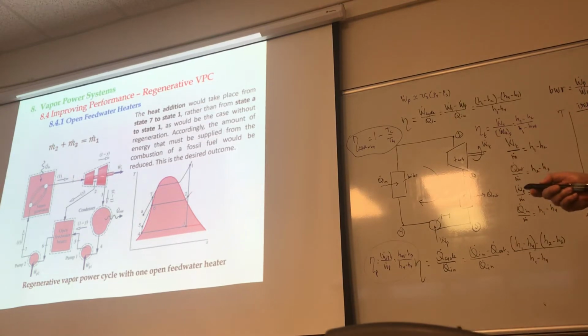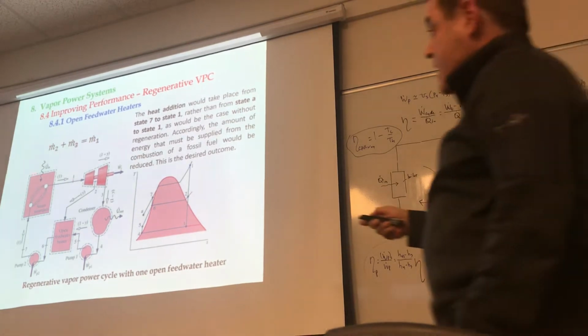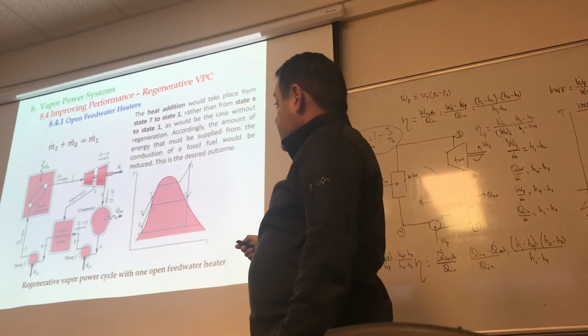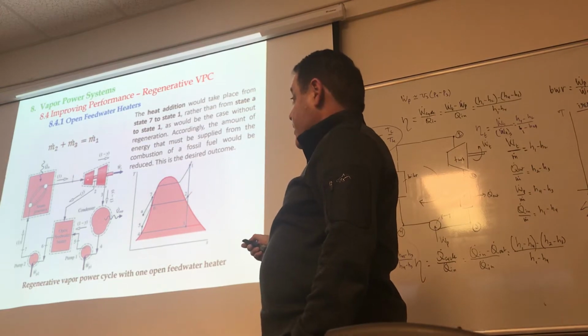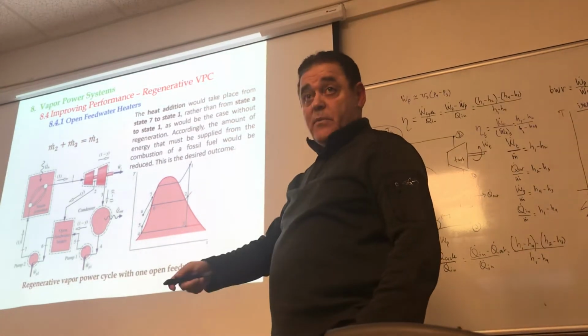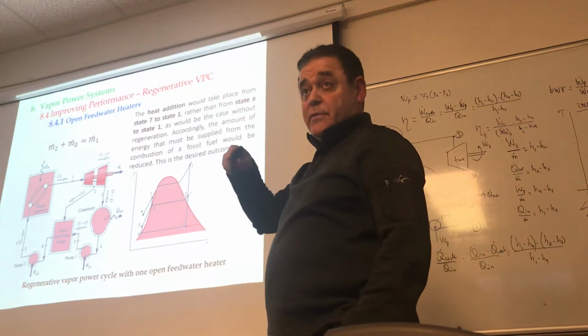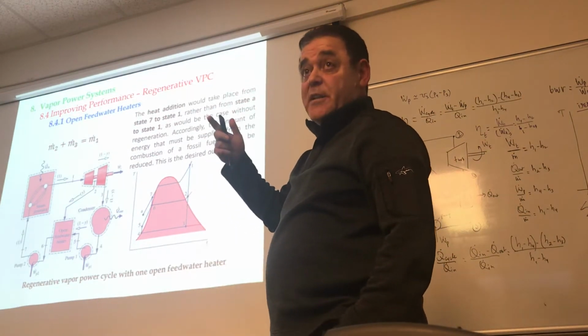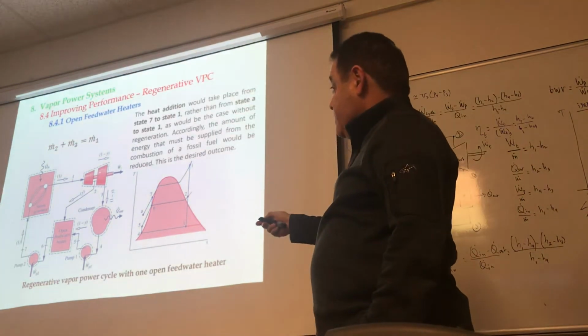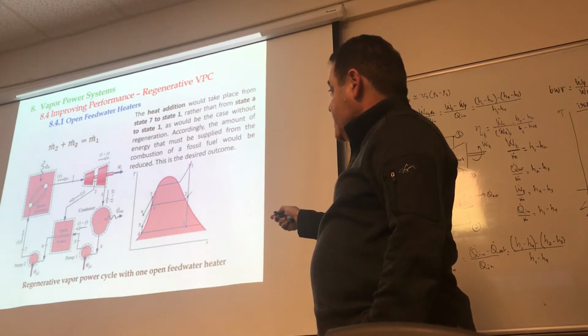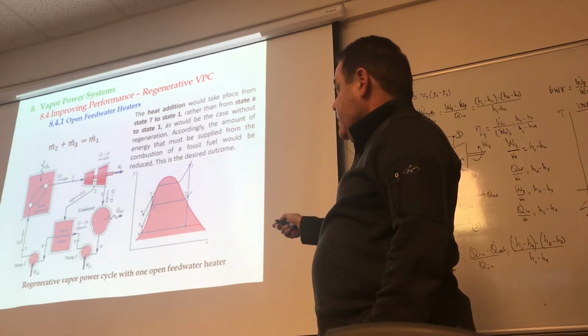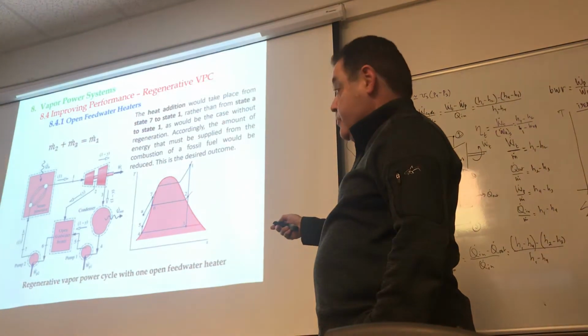Then I come back in here and I see what? How many stages? 2 stages, okay? That means my mass flow rate is coming in like this, right? And it expands through the first turbine to where do you expand? Do you expand to the lowest pressure or an intermediate pressure? Better be an intermediate because we haven't finished our expansion. So we come in between 1 and state 2, okay? Between 1 and state 2, what did I do? I came down isentropically to the intermediate pressure.